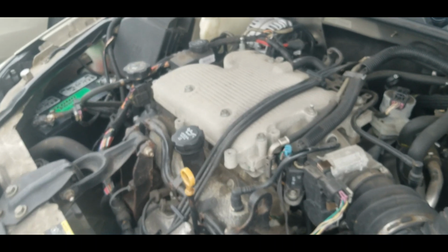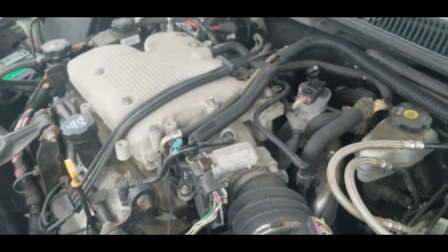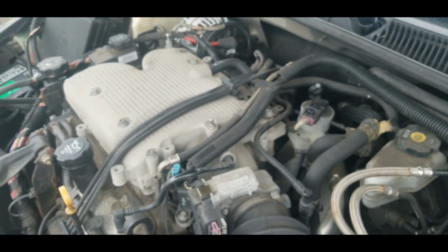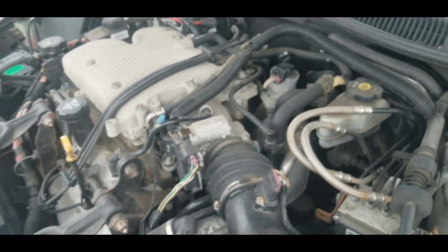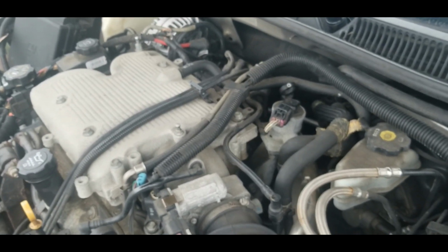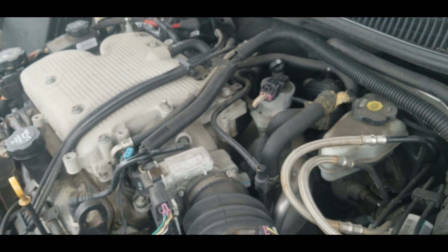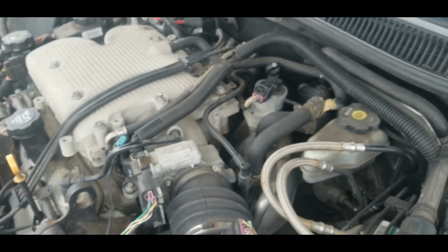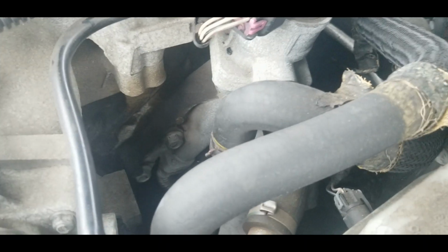the car most likely burns a little bit of oil, which creates a buildup in the exhaust valves, and that clogs up the ports for the exhaust gases to get out of the combustion chamber and go to the exhaust system. So what else will it clog up? It will clog up those little channels that the secondary air injection system uses to put the air into the